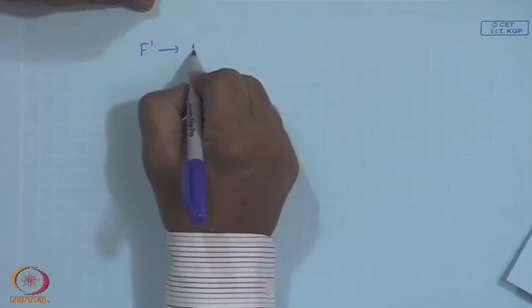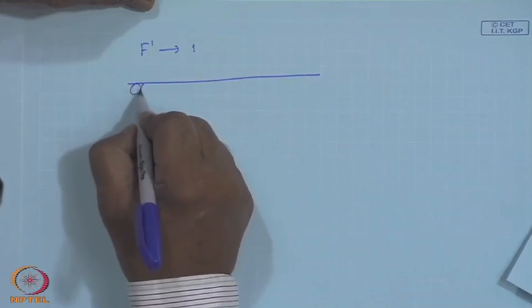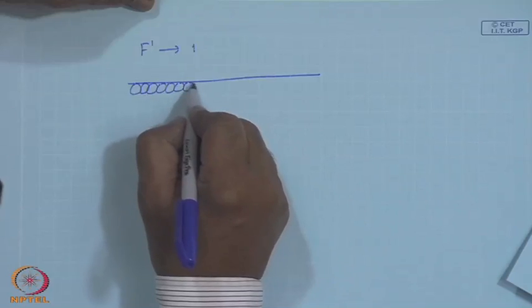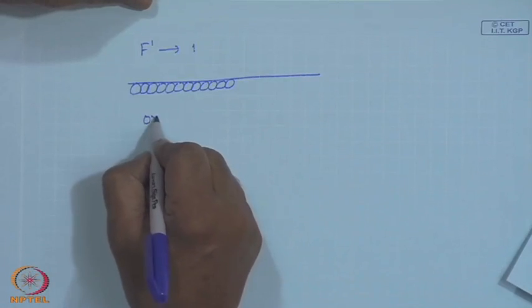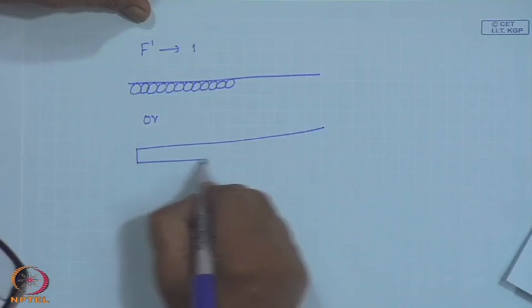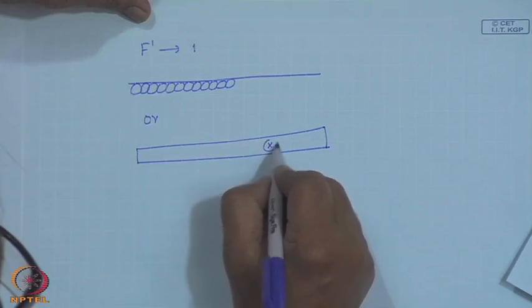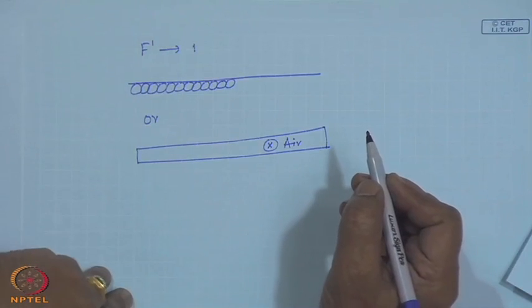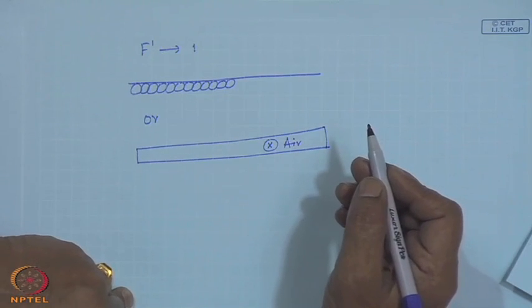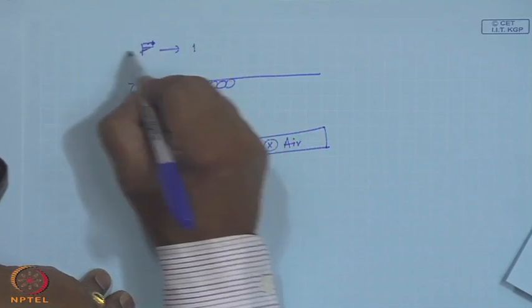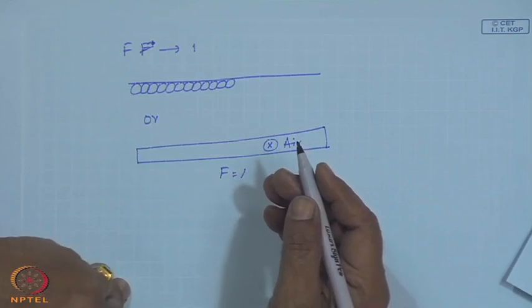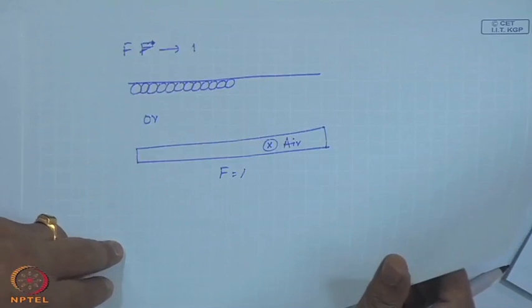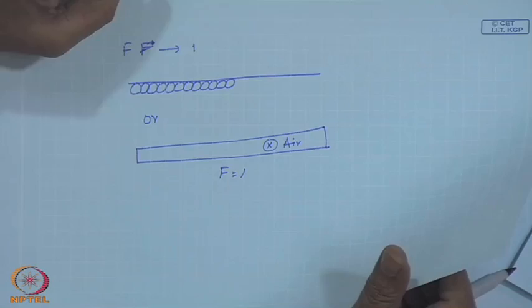In principle, one can make F dashed go to 1. For example, if I have tube to tube, a large number of tubes, this F dashed will tend to 1, or for, let us say, an air heating collector, this may be only a duct with the flow perpendicular to the plane of the paper, and here also the fin efficiency will be 1. Consequently, your F dashed also will be higher. So, this is only to emphasize that your collector efficiency factor is not an efficiency.